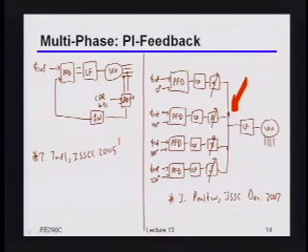Make sense to people? Maybe this doesn't matter, but any mismatch on the feedback paths, or at least for the dividers, I guess the CDR adaptation takes care of it? Well, no. If there really was mismatch on the feedback paths, that could translate into errors on the step sizes of your phase interpolation codes.